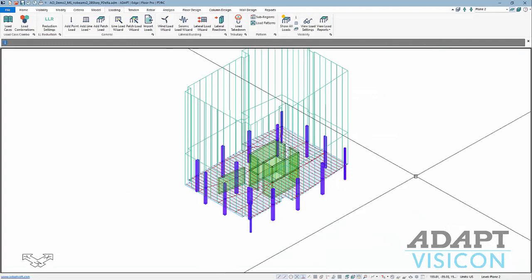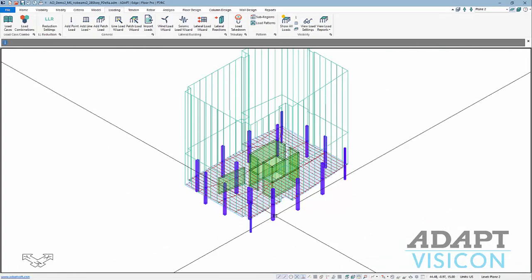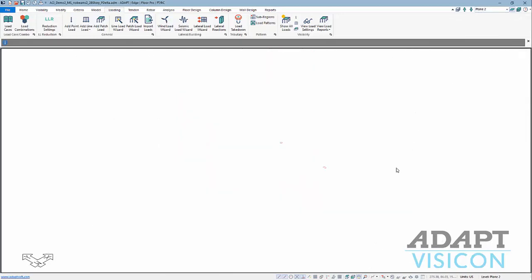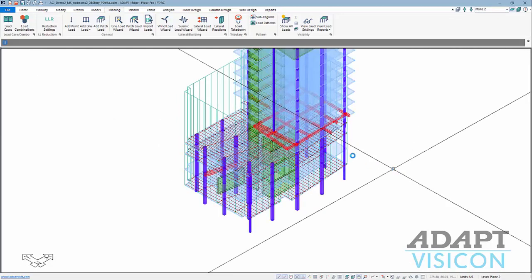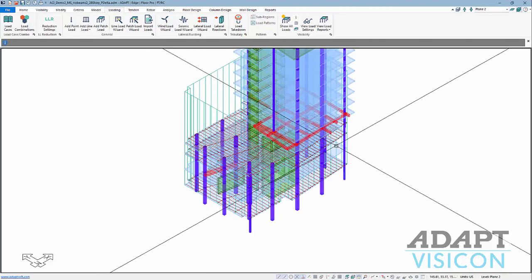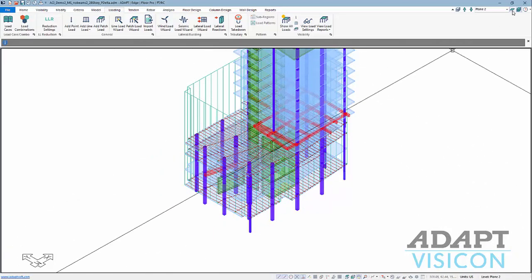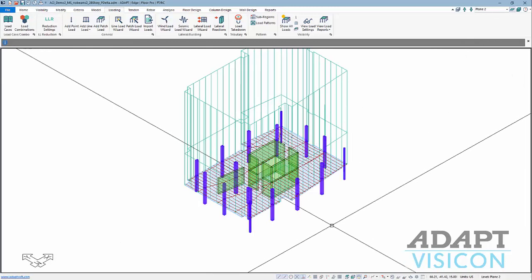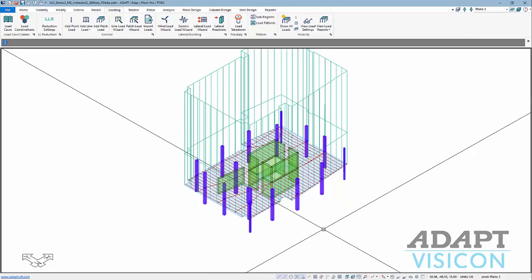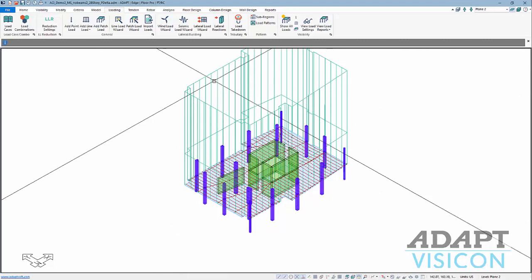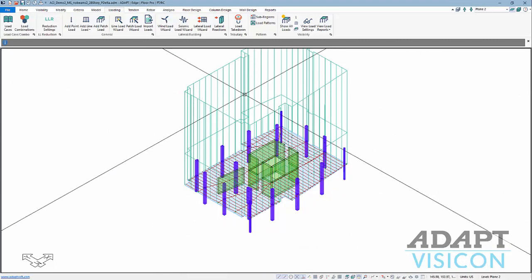So we'll go ahead now, and we're going to be using a PT slab here. This is a single level slab. It's actually occurring on plane 2 of a multi-story structure. So to check punching shear, we can do this various ways. We could develop the check based on a global solution of an entire structure, or we can go to a single level and just run that particular level in isolation to check punching. So the first thing we want to do, obviously, is to model the slab, load the model, and we'll assume that that's been done on the user side.